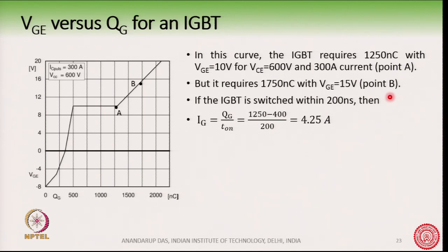The area under this curve is about 1750 nanocoulomb. So, this much charge will be required to turn the device from fully off state to fully on state.